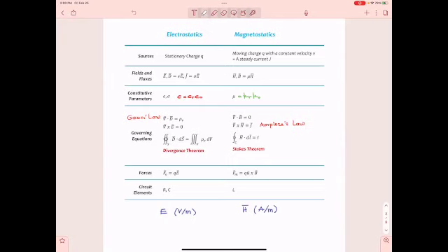And if the material is, as we said, linear, homogeneous, and isotropic, then mu is a scalar. And mu is going to be mu sub r times mu sub naught, where mu sub naught is for free space. But mu sub r, which is for good magnetic materials, is a very, very, very large number.